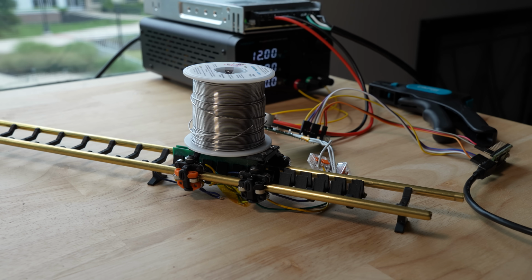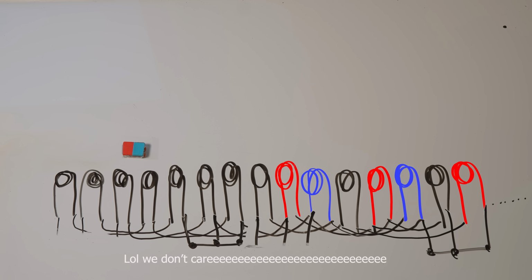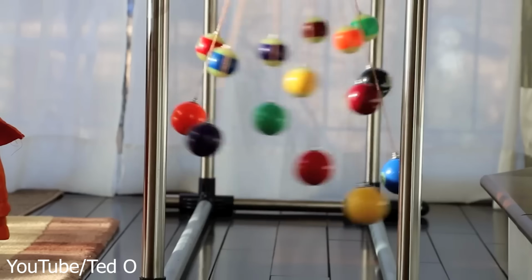Occasionally, the train will vibrate in place, and this is because I'm doing something called being lazy. Remember that the synchronous part of LSM means that the coil control needs to be very precise to move the magnets forward, and without any feedback on the magnet position, I have to resort to using physics and calculations. But because of pesky things like resistance, friction, thermals, often the ideal acceleration profile is not actually ideal.